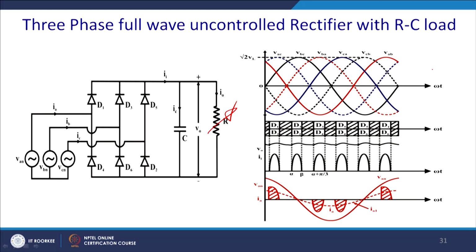Similarly, this is a 3 phase waveform as we have discussed. Here, as long as the input voltage VAN is less than VAC, the diode will not conduct, so the output voltage is held by the capacitor and has this kind of value. We will have ripple that depends on the load current as well as the size of the capacitor.